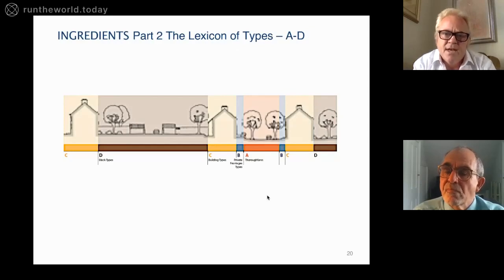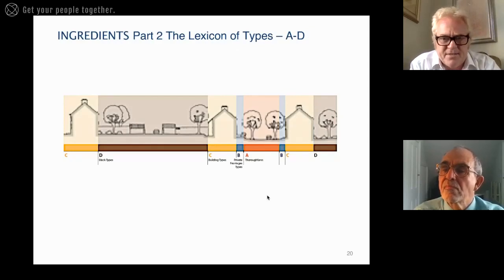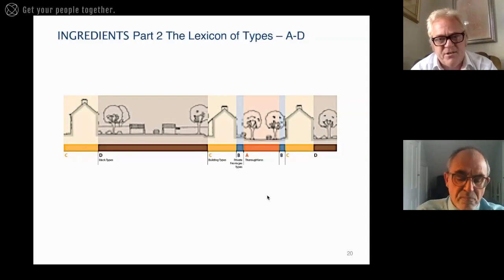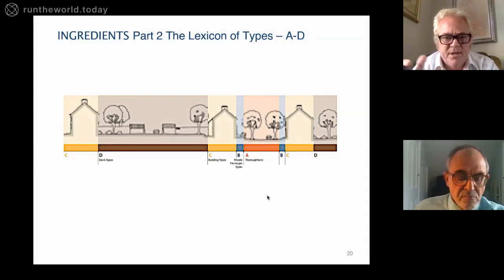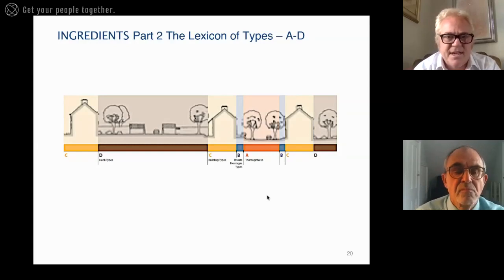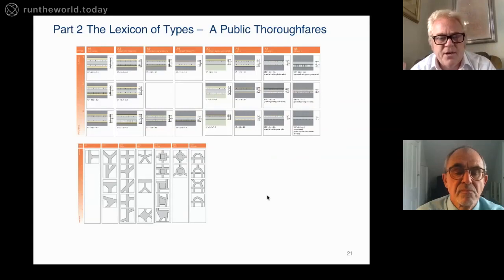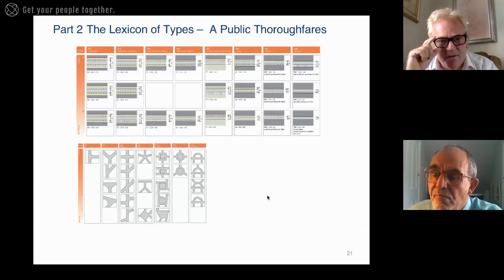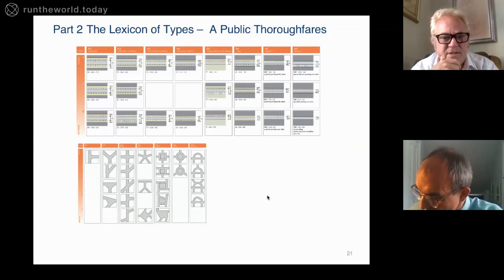This is also then the ingredients. So this is like the ingredients of the recipe, and this is a cross-section through a street. So obviously you get the street, you get the setback, which we call public thoroughfares. There's then the private frontages, which is the boundary between the ownership boundary and the setback. There's then the building type, and then there's the block typology, which deals with servicing in the back. So here we go. A is therefore all of the things to do with street widths, parking standards, verges. This is really useful because if you work with the county or authorities on this, you essentially get pre-adopted street and parking layouts. So when you go to write your code, you've got as good as reserved matters.